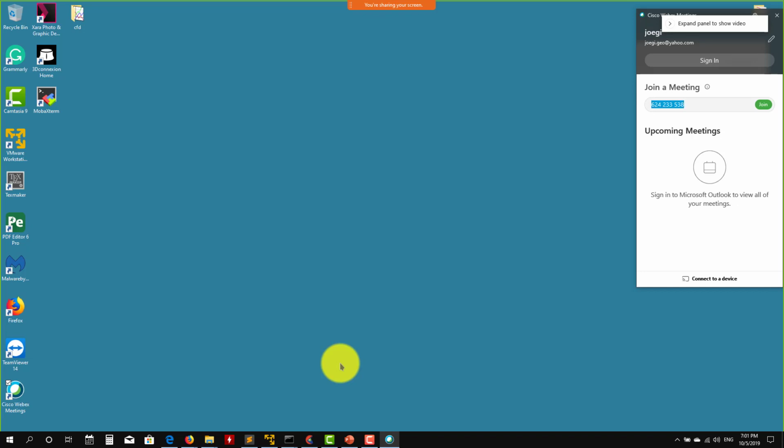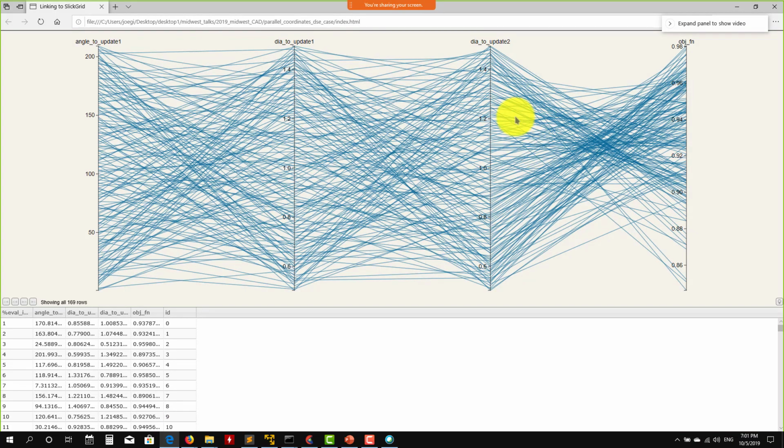Actually, everything depends on the resources you have, but let me show you something here that we have. You see here that we run with 3 design variables. Okay, so here we have a parallel coordinate. These are about 150 simulations. To get this, it takes a computer with 32 processors, which is something that you can find today, about 3 hours, okay? So you do concurrent tasks, everything. As you see, it's very affordable, okay? You have the resources, be careful, plan everything and distribute.